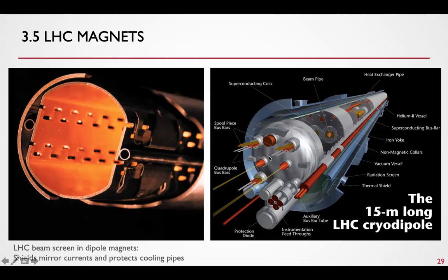The soldering had to be developed. You cannot really solder superconducting cables. It's very difficult because the soldering material will not be superconducting. We have nano-ohm resistance between these junctions. And nano-ohms times 20 kiloampere is what is carried away by the cooling of the superfluid helium.